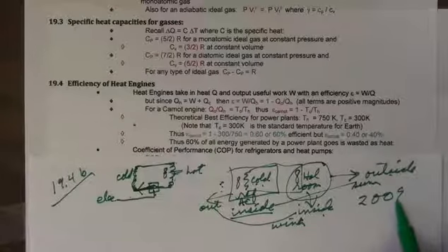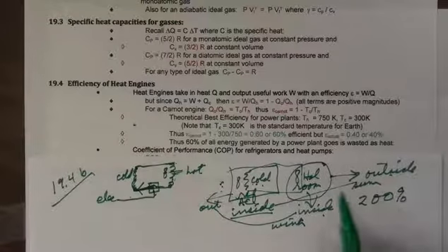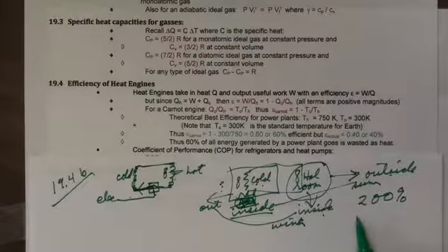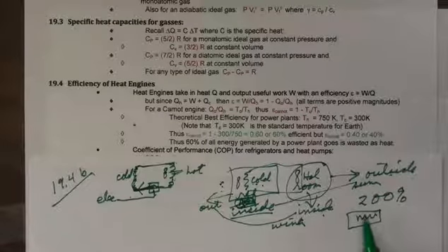So it has an efficiency of 200% over just taking the electricity that we're putting into the system and using a straight heater to heat. So you're much better off doing this than having a heater. If you go to a cheap store and buy an area heater, it's going to cost you twice as much to heat in South Carolina than it would cost here.